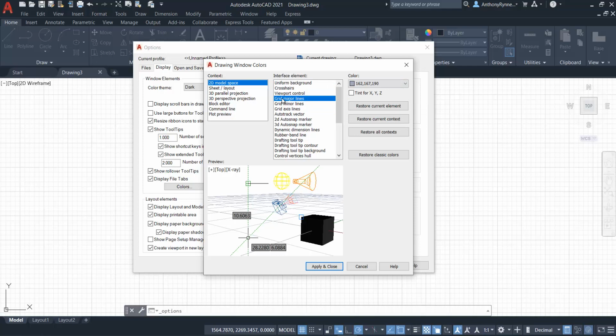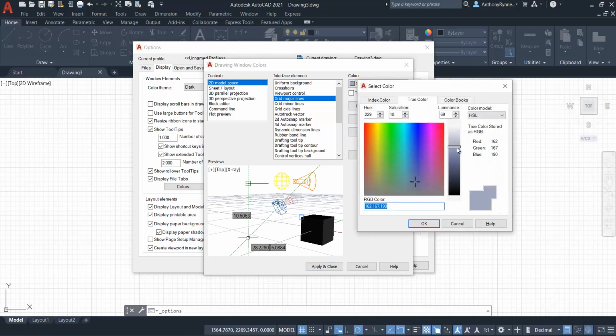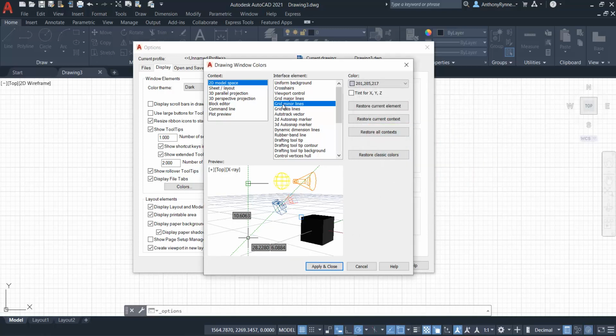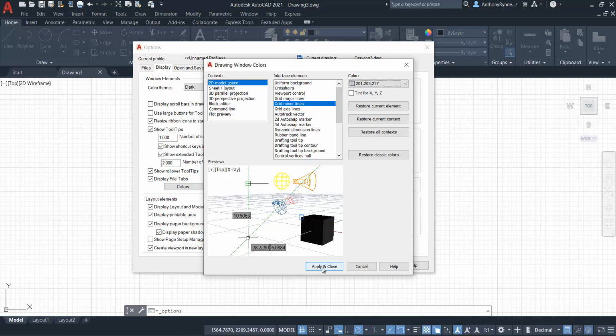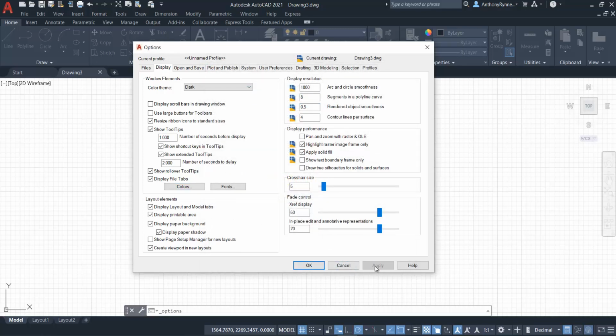The other thing that you can experiment with are the grid lines. So we have major grid lines and minor grid lines. For the major grid lines here, I have gone in here and selected color, and I've just used the slider here to lighten the grid lines. Somewhere there, it doesn't really matter. Place the slider there, and that's my major grid lines. And then my minor grid lines, I want them a little bit lighter. So again, select color and drag the slider somewhere there. So this will lighten your grid with the white background. So apply and close that and apply and click OK.